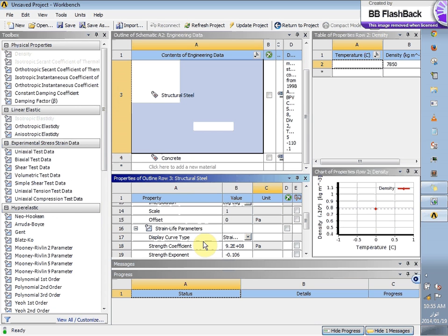But let's say you're not interested in that analysis. You want to analyze wet concrete when it has air bubbles inside and it is workable and behaving like a foam, and you want to see what happens to the concrete there. It's more like material engineering rather than structural engineering, and chemical engineering again, because there are chemical reactions going on and so many other things. In that case, you want to add some hyperelastic properties inside concrete too.